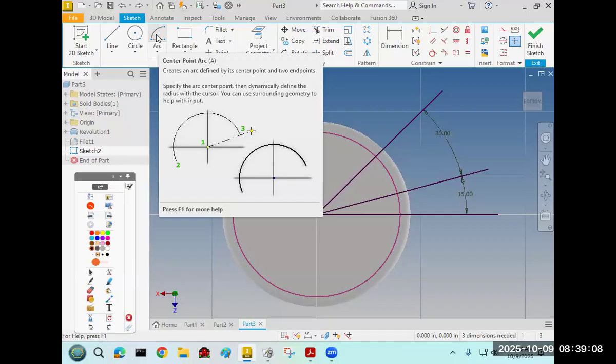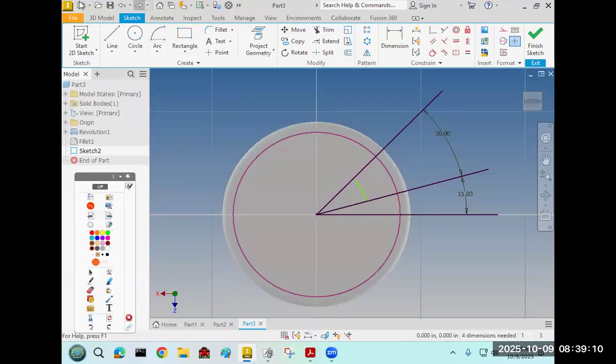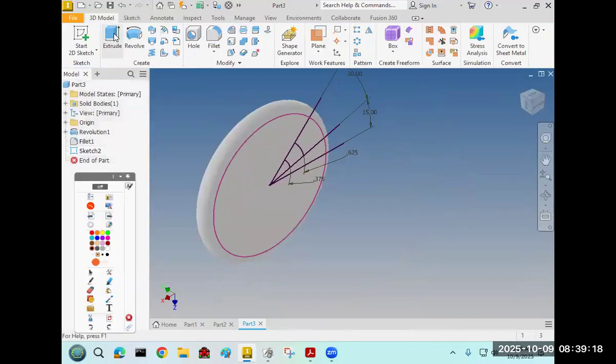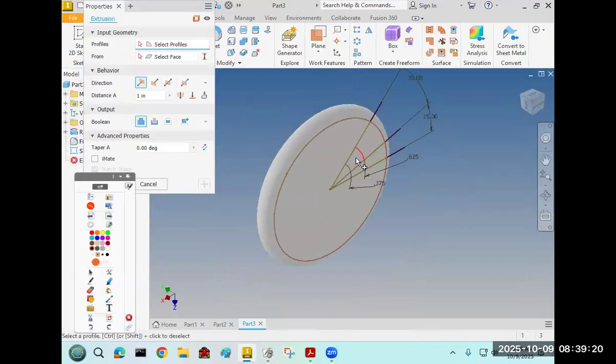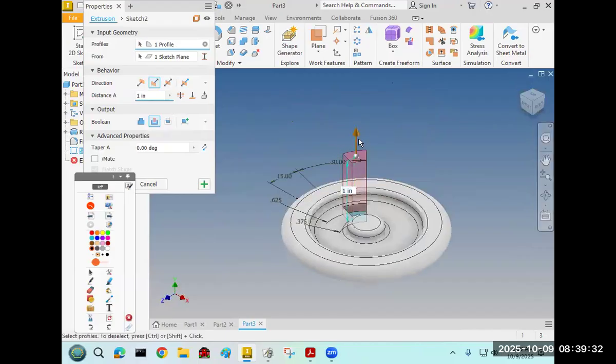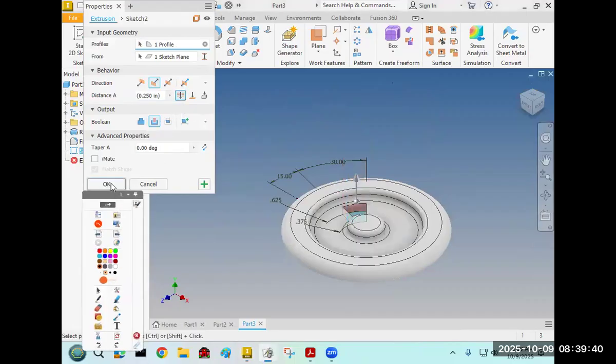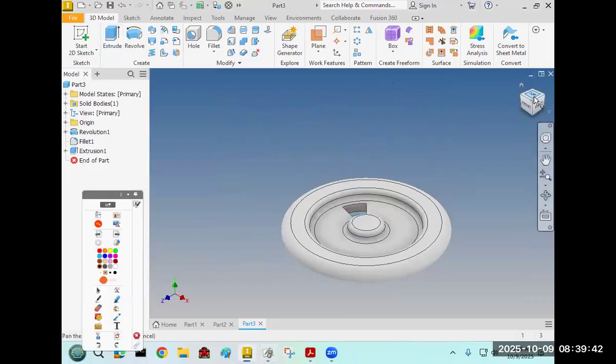Okay. All right. So we've got our shape. We're going to finish sketch and extrude, and we want to extrude that shape we made, but just one of them. And we don't want to create material. We want to cut material, and for the depth of cut, anything more than 1/4 inch is going to be the right amount, but the pro way is just through all and hit okay. Okay, so now we have one of these.